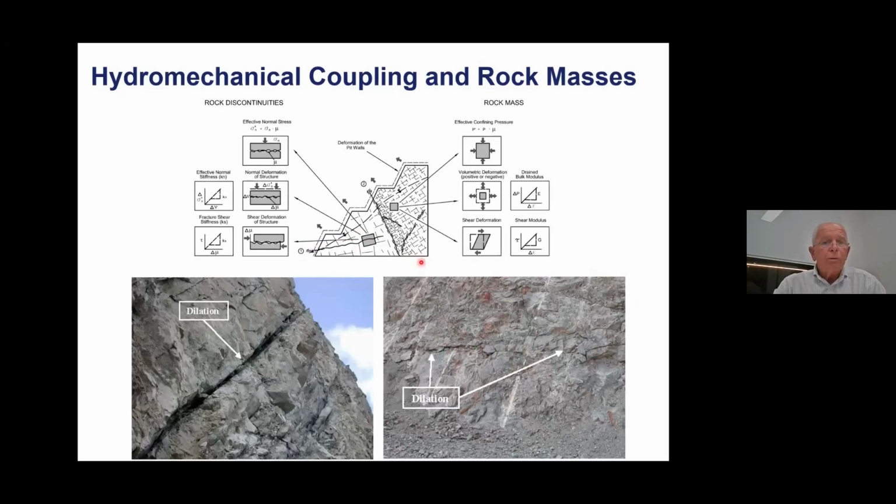Go to point 2, where we've got a fault, so quite a continuous structure in the boundary between the very jointed rock mass and the poorly jointed rock mass. And again, you can see the aperture that's generated from the dilation. It's a shear movement in a toppling mode, and it's related to just bulk movement of the whole mass as we excavate. But the result is this dilation.